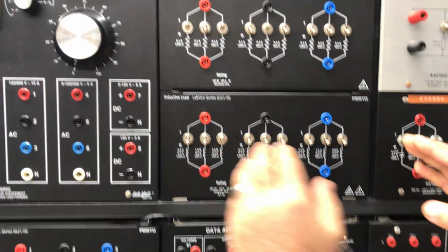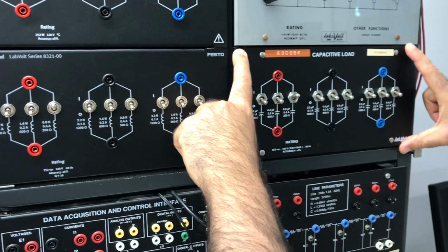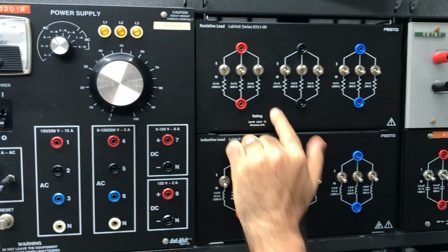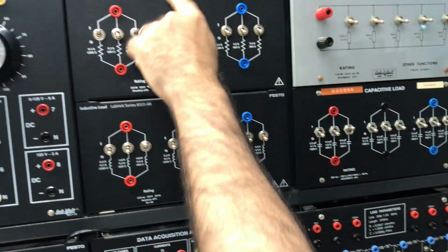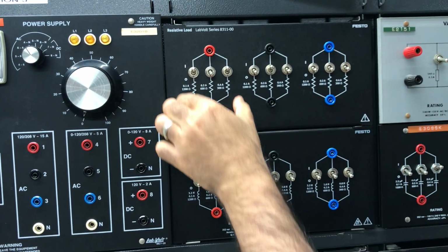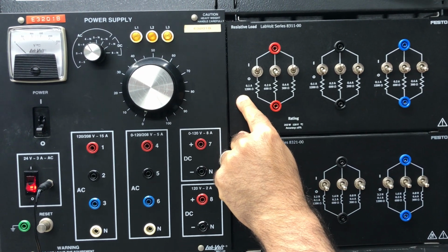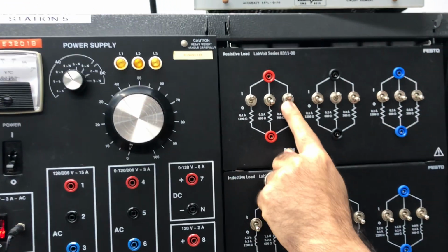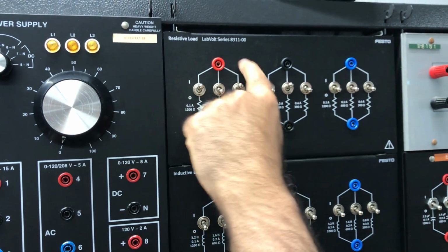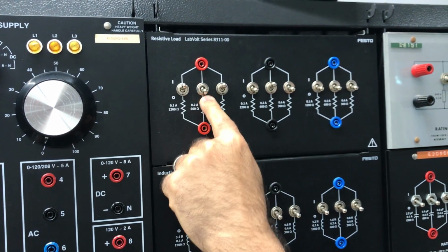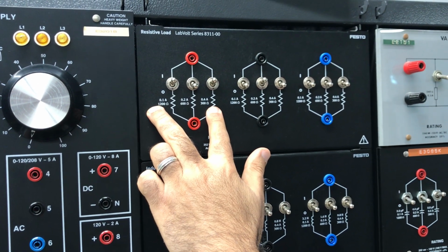We are going to do that using this resistive load, and this inductive load, and this capacitive load. So I'm going to use only one phase, which is this one. I'm going to use this phase, this phase, and this phase. So this branch is representing a resistance. I have 300, 600, 1200. I need 240, so I'm going to take this one on, and this is off. So those are connected in parallel, and this is open circuit, so I don't have this one. The total resistance of those will be 240.